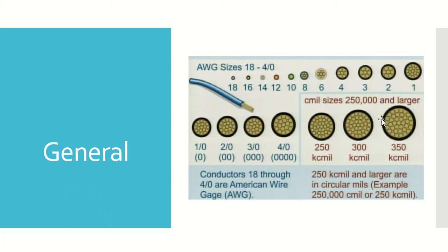So first thing I wanted to point out was, obviously the larger the conductor, the more current it's going to be able to handle. And we'll see that especially in all 3 different columns. There's a 60-degree column, a 75, and a 90 degrees Celsius column for this table here. And just take a look in your code book as you begin to go down this chart. You can see that the conductor ampacity begins to increase significantly.